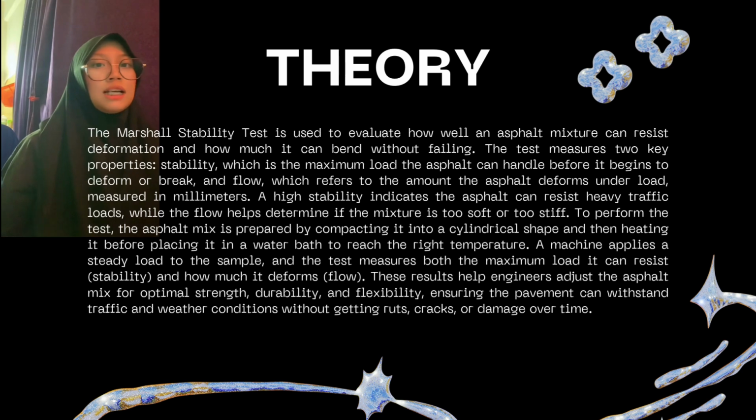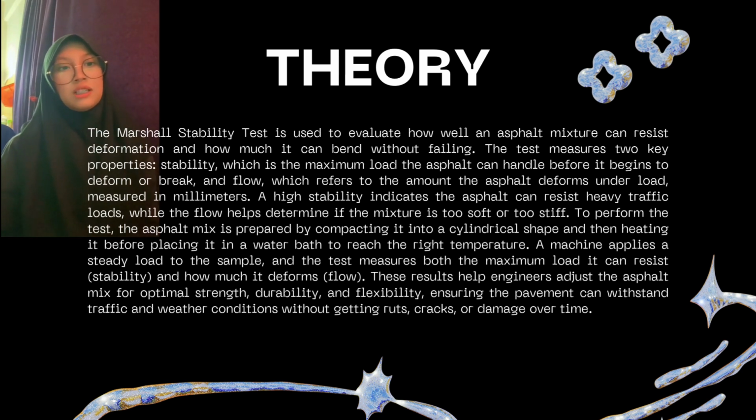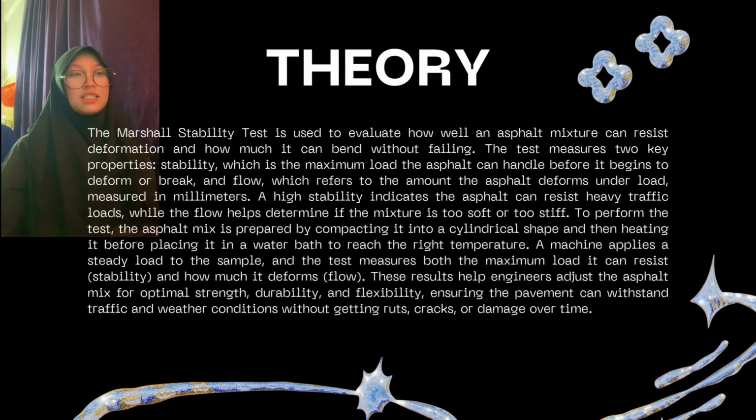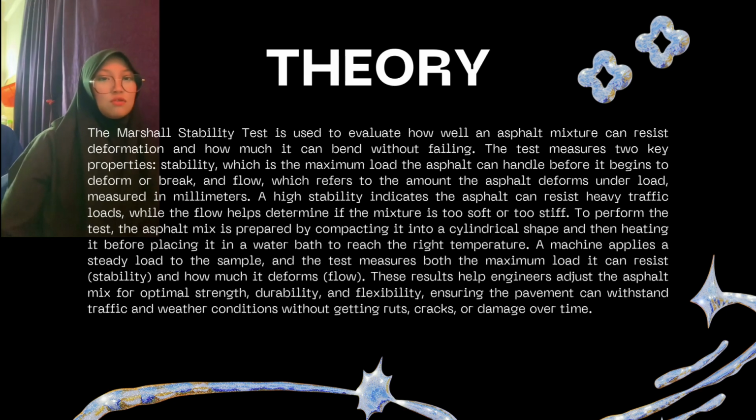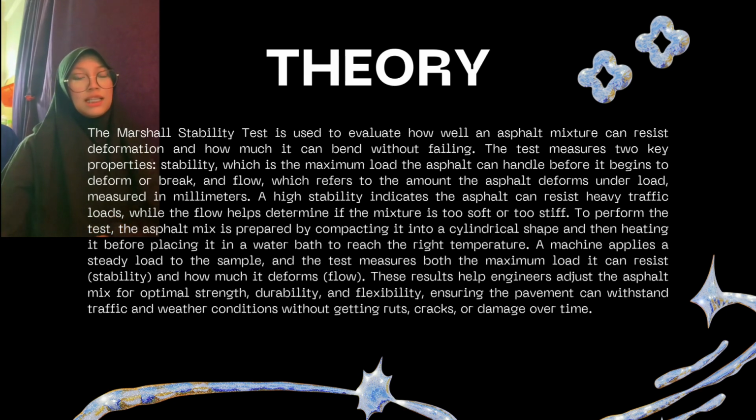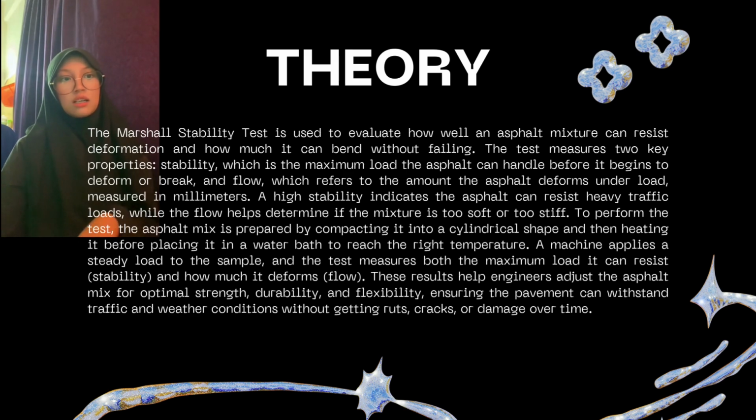A machine applies a steady load to the sample, and the test measures both the maximum load it can resist, stability, and how much it deforms, which is flow. These results help engineers adjust the asphalt mix for optimal strength, durability, and flexibility, ensuring the pavement can withstand traffic and weather conditions without getting ruts, cracks, or damage over time.